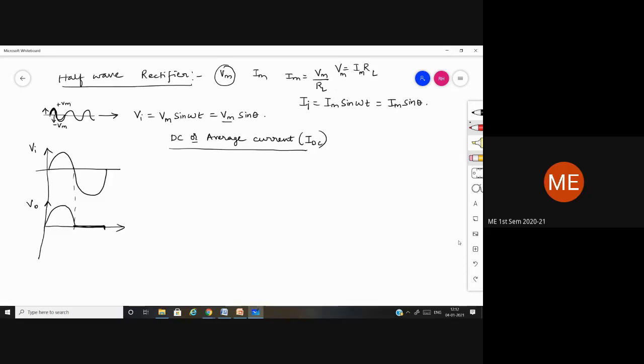Now, when you are using a diode, does the diode have some resistance in it? It has some resistance, right? That resistance is known as RF, the forward resistance. In the beginning of the class, while telling you about 0.7 and 0.3, I told you the junction offers some opposition. That opposition is nothing but resistance. That resistance is the forward resistance. And we are having the transformer.